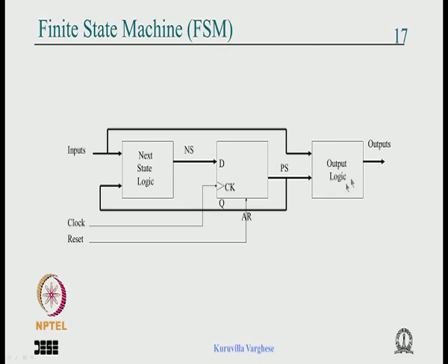Similarly here, because the output is a decode of the present state and the input, if you do the assignment in such a way, can this logic be minimized, or is there an assignment such that both can be minimized, giving a very great saving in area? If the area is reduced many times, the interconnecting wire length can be reduced, the delay will be less, and the power dissipation will be less.